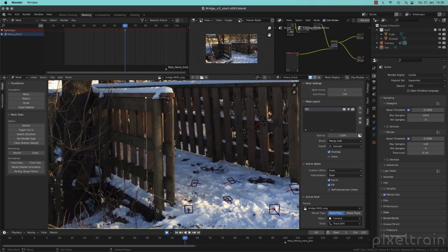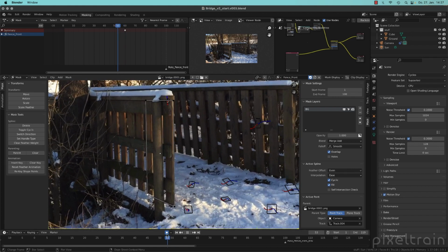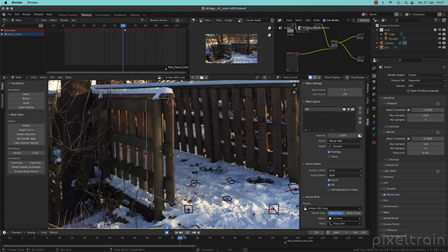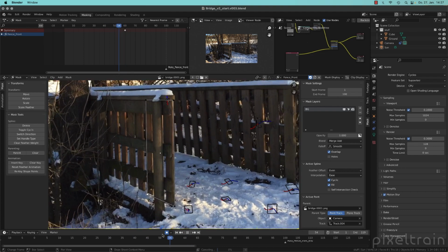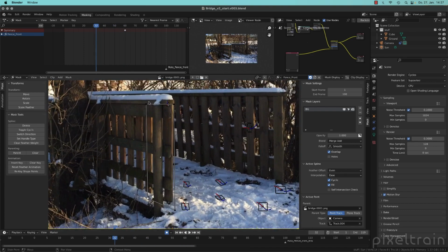We can check that by clicking through them here to this movie clip, to this camera, to tracker number 4. If you have named them nicely, you can open this up, and here you see our helpers, and then you can see helper, big shape, or whatever. What now happens is, if I now move my time indicator, you see, this is not the best example, but you see everything is moving now accordingly with that. For these 2 trackers, it helps. It's nice. You still can make offsets.